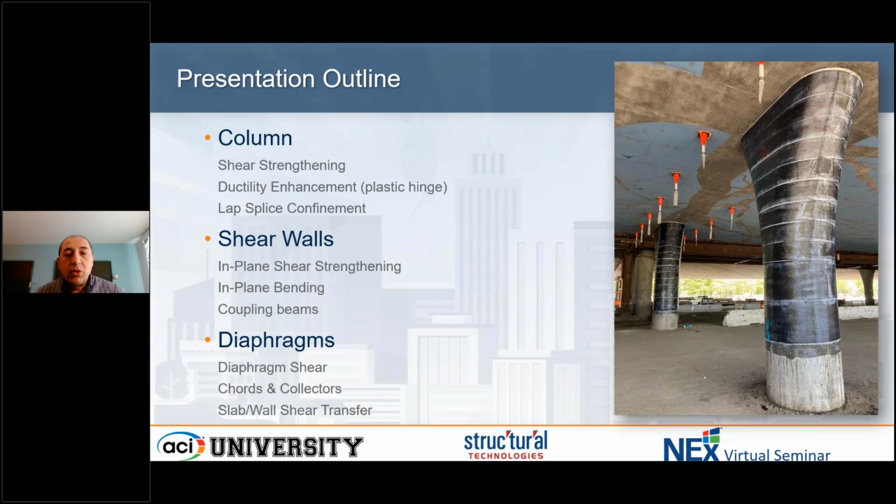So seismic is really a very complex topic because it includes lots of pieces: the approach for the analysis, determining the demands, the importance of the structure and what kind of performance we're looking for. And then after that, the design of the FRP or any other structural system, maybe not just FRP: concrete enlargement, steel components, steel plates, jacketing, etc. for the strengthening.